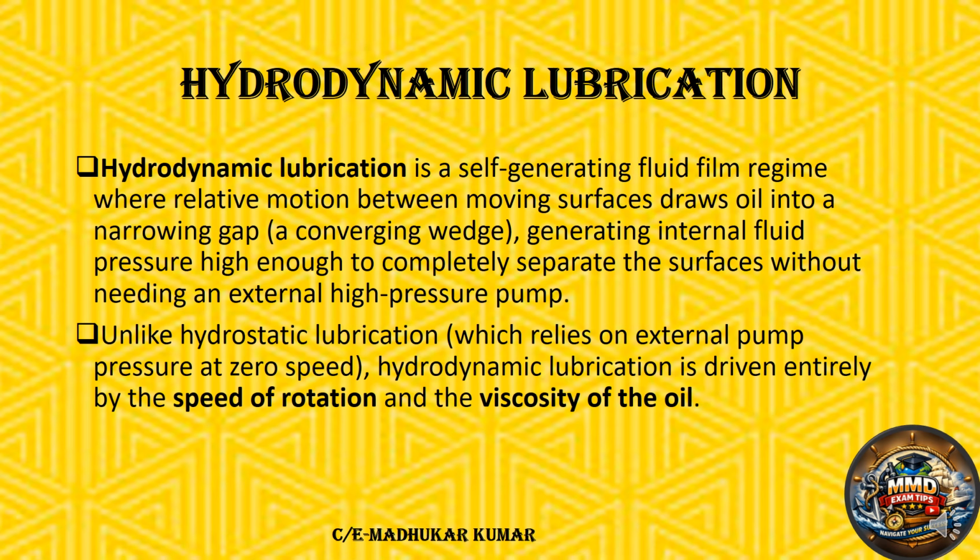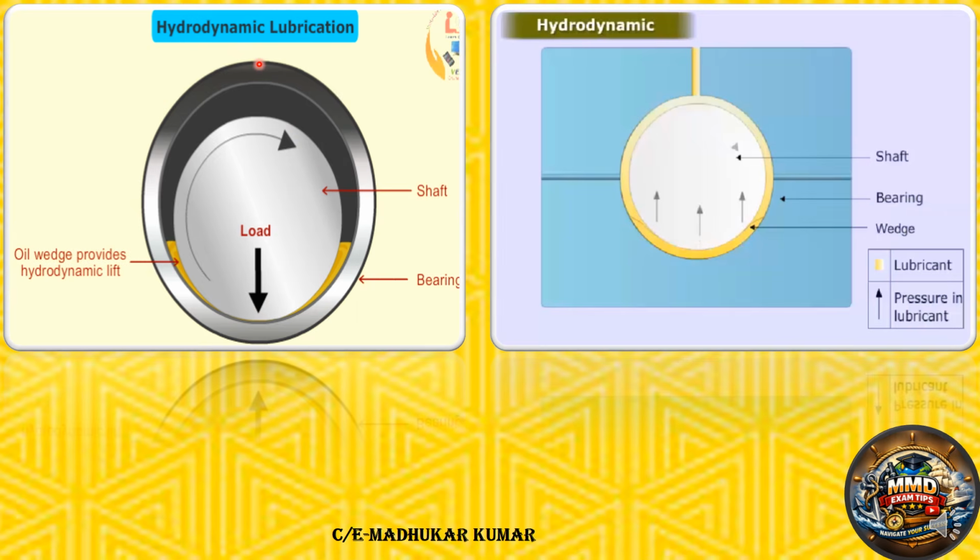We will see this. Here you can see the hydrodynamic lubrication. You have the bearing part and you have the shaft or the journal part, and the lube oil is over here. The load is directly on the bottom, and this is at rest. But when it starts with the motion, it creates the lube oil film and there will be a separation. I will show you that also. This is the starting condition part. Here you can see this is your shaft, this is your bearing part, and the separation is there. So the lube oil already floats in between.